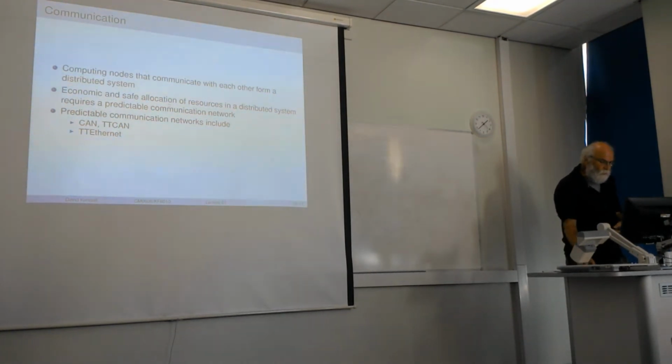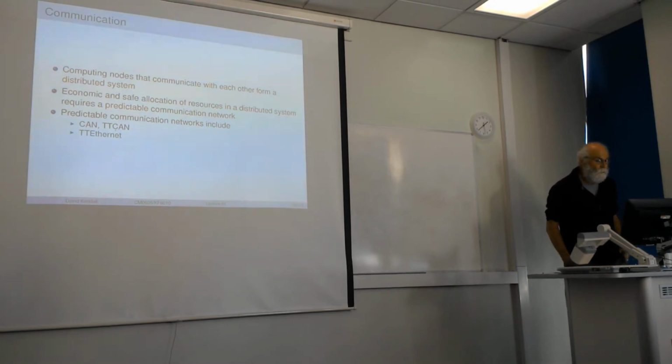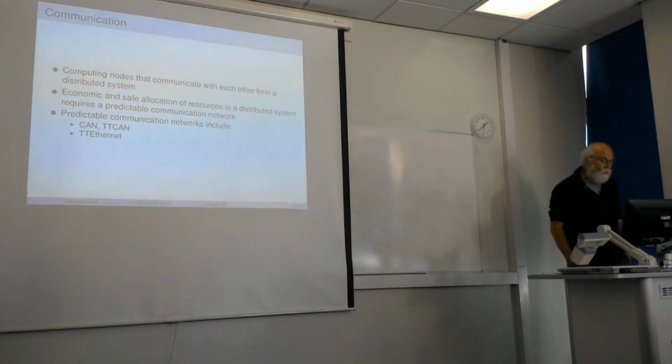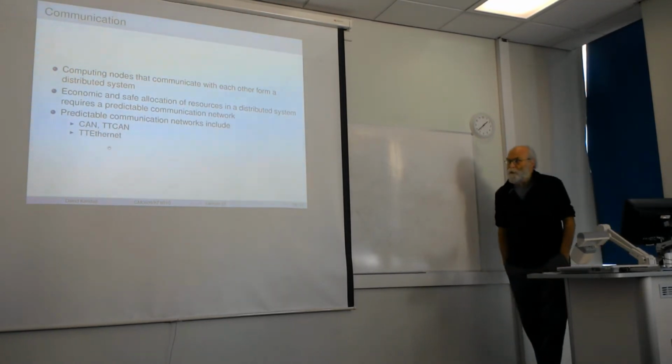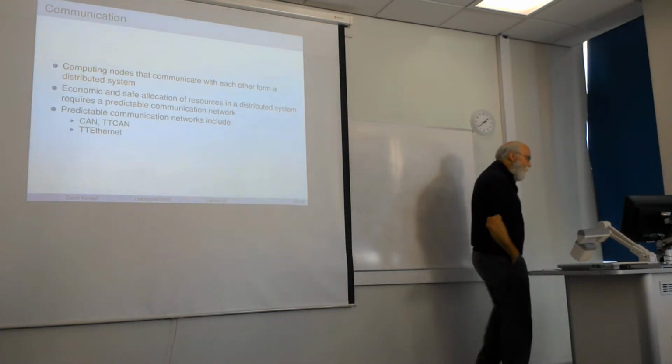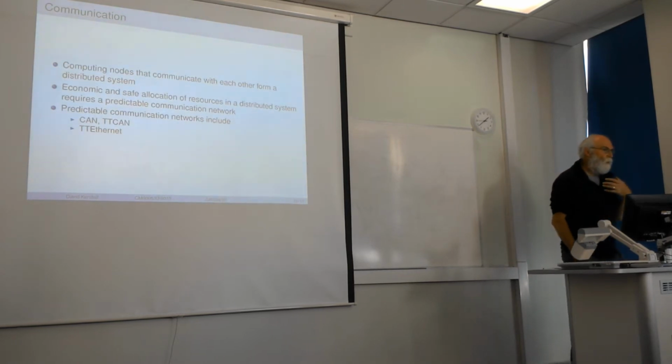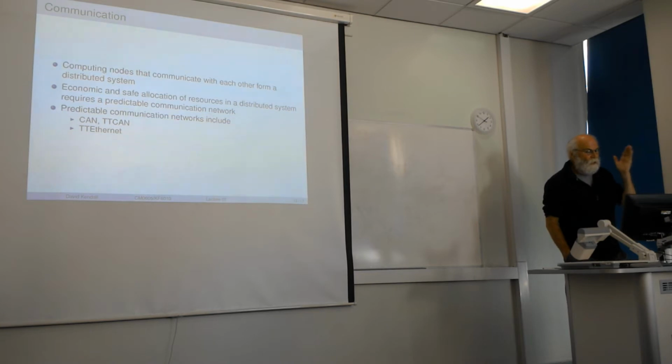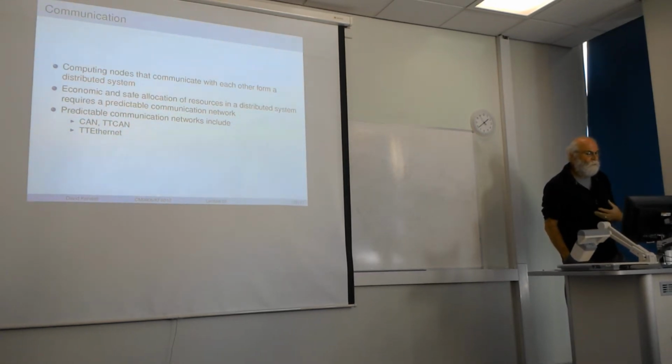We've got a slightly different variant of CAN called TT-CAN, time-triggered CAN, which adopts, as you'd expect, a time-triggered approach to handling the access to communication. And more recently, there's been quite a bit of work on time-triggered Ethernet, which takes essentially an Ethernet approach, but it ensures that collisions don't arise because nodes are given a time slot in which they're allowed to transmit,